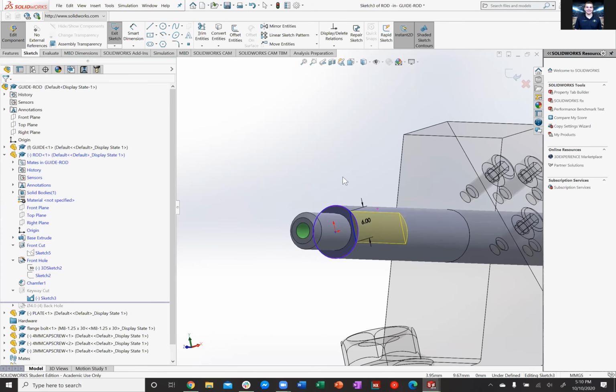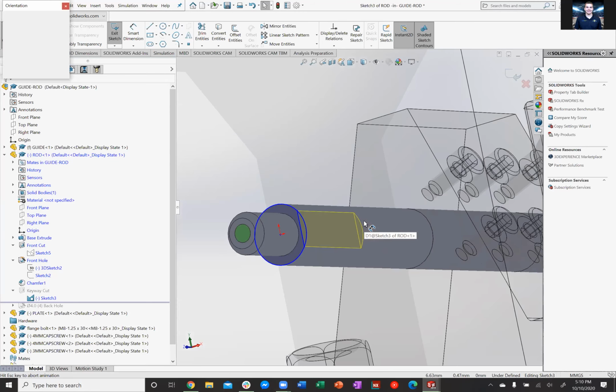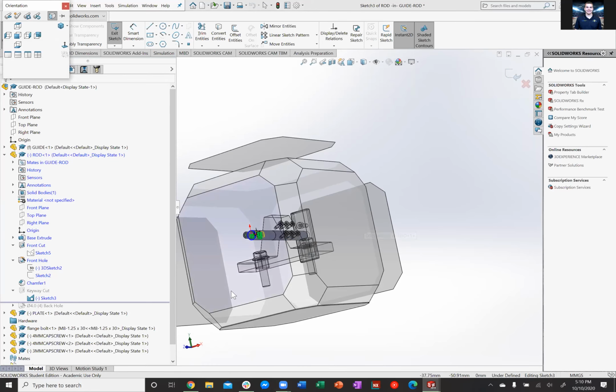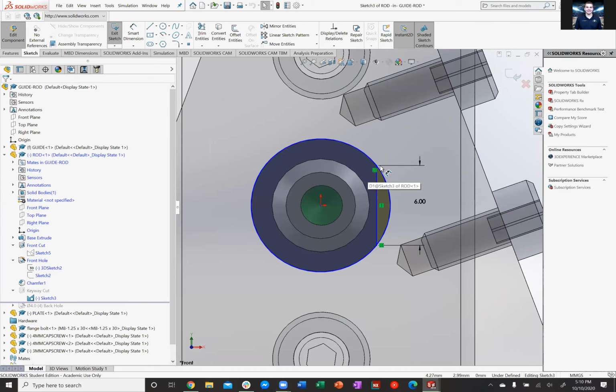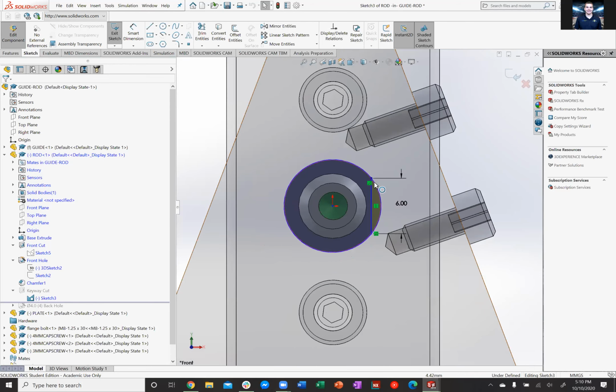Although it's going to be round and this part will be cut away, when you make the part, you still want to have it lined up. So you click on the front or whichever plane or orientation. That way, when you make the drawing, it's not at some weird angle for the manufacturer to get confused. So this line is vertical rather than just drawing a random line anywhere.